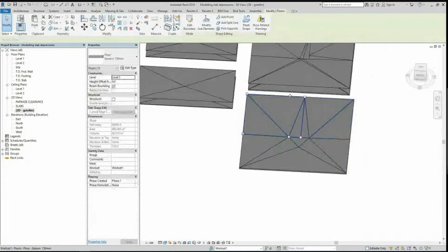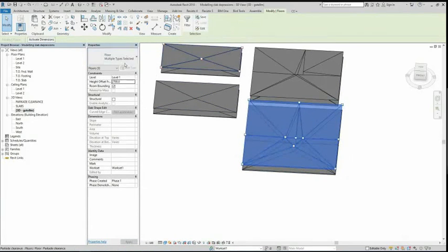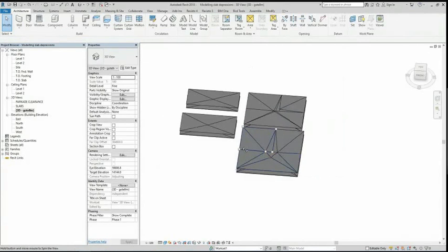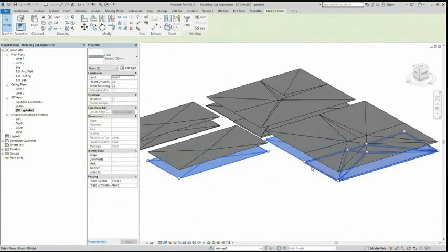So I'm going to select all 3 again, and just move those up to 2700. And again, as the next step, I want to just switch that to a parkade clearance. All right. So now that I'm in the coordination 3D view, I want to make sure that I've made my slab elements all the same work set, or the correct work set to show up in the slab 3D view. So I've selected all 3. I'm going to set them to slab work set, sorry. And now they are slabs.